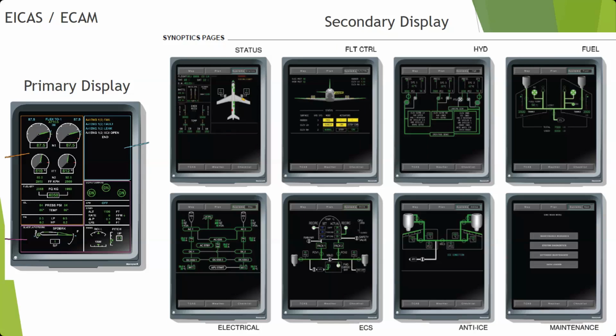That's really handy. Pilots had something pop up in flight, but it came up and then it went away. The plane lands on the ground, and you're like, yeah, I can't duplicate it. I have no idea what to do. But now with maintenance pages, often they log those faults. You can go back and look at what came up during the flight, and see what was recorded in the computer. That's really handy when you have intermittent faults or faults that only occur when the plane's flying.